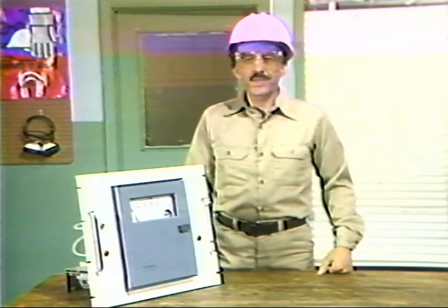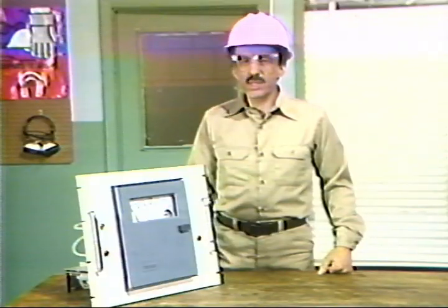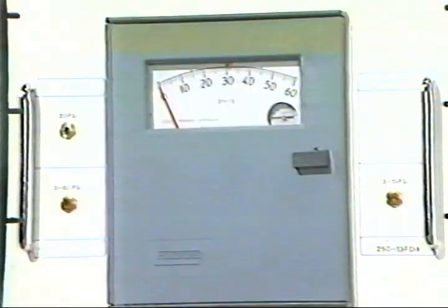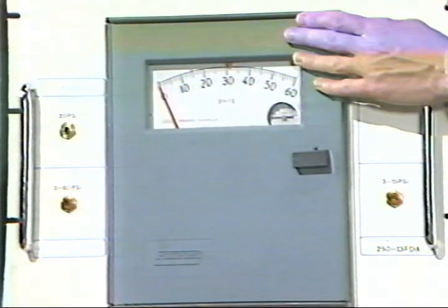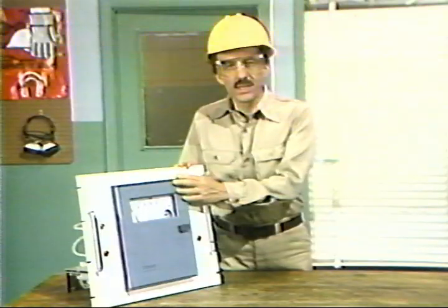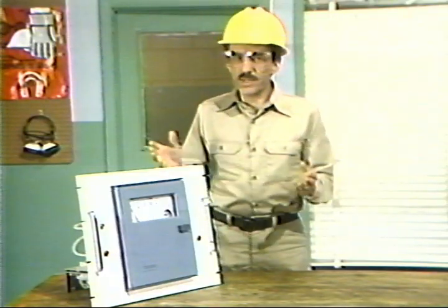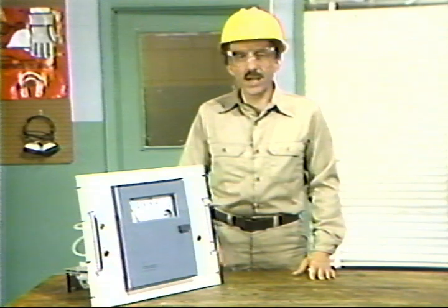In some processes, it's important for the control system to quickly stop any deviations in a process variable from set point. Now, one type of controller that can do this is a proportional plus rate, or rate controller. A rate controller projects how much the process variable will deviate from set point in a given period of time.